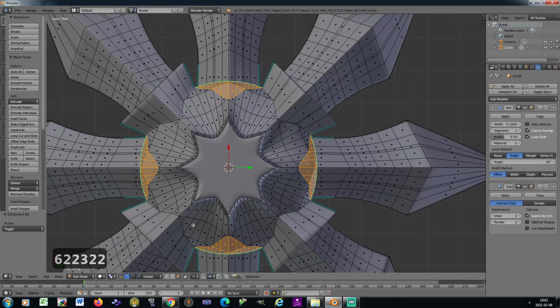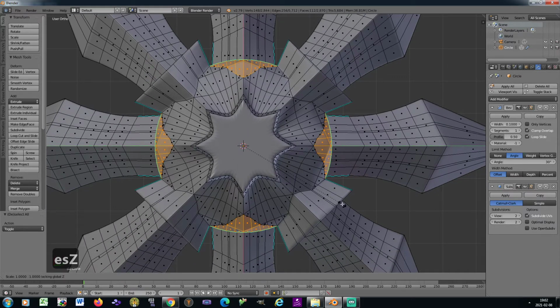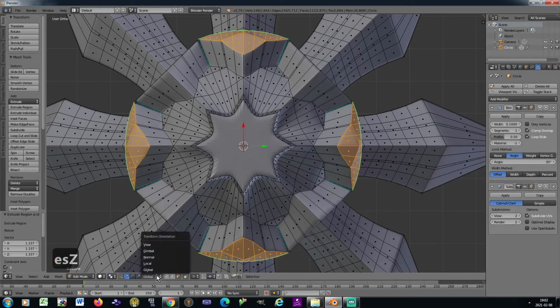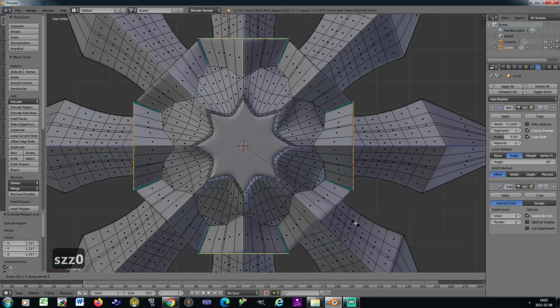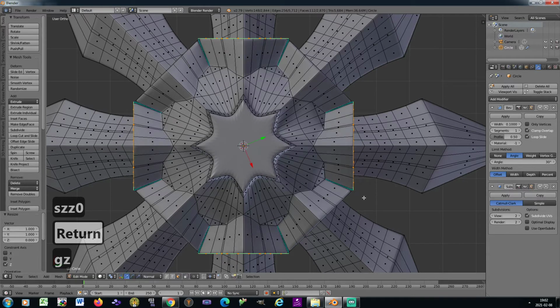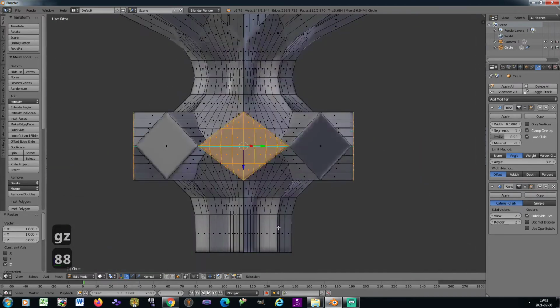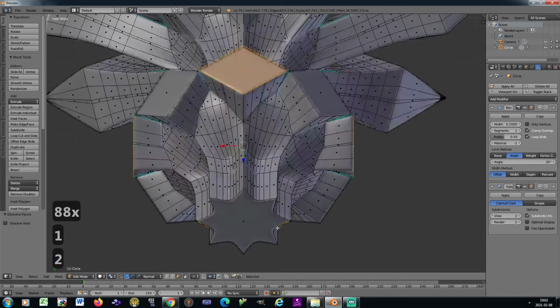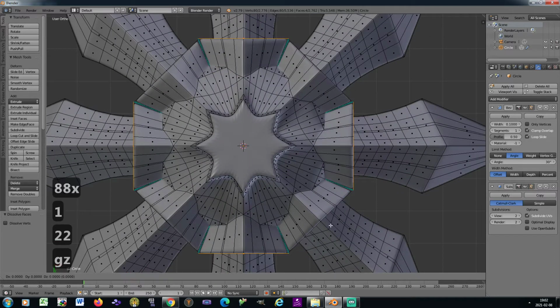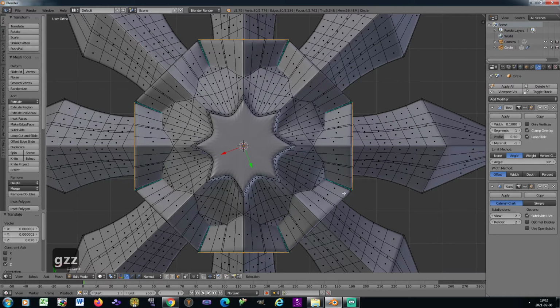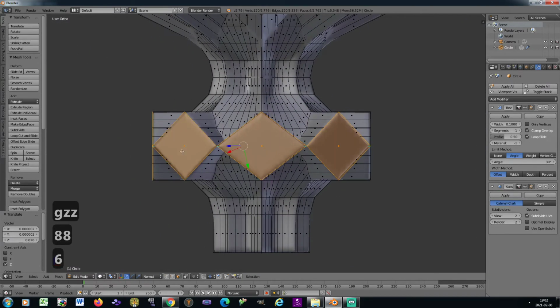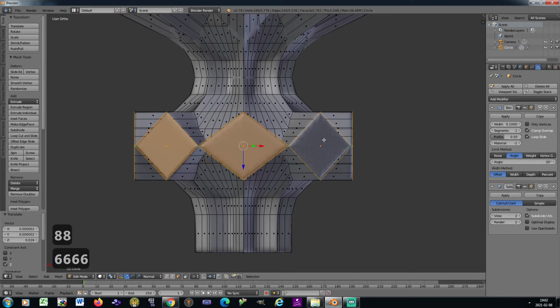And extrude and scale along the X and Y axis. And scale them down to 0 along their normal Z axis and move them up. First, dissolve faces, so that they're even with the others. Grab all 8 faces.